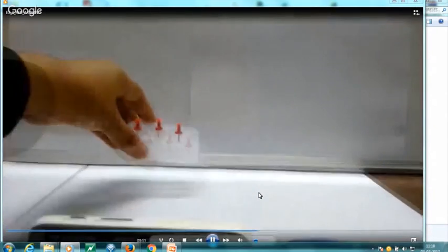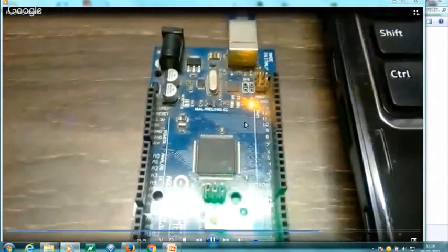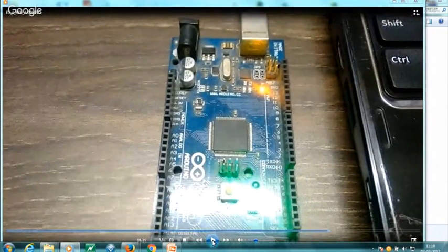If I put a red object in an image, you will get this value from your webcam, and it will transmit to your system, your MATLAB window. Now a beep sound is coming, that means your MATLAB is getting it, and now you can see the LED is turned on. This simple example shows you how you can send your command according to your image processing. If you recognize a character, you can send that value to your Arduino board. You can perform different types of applications.